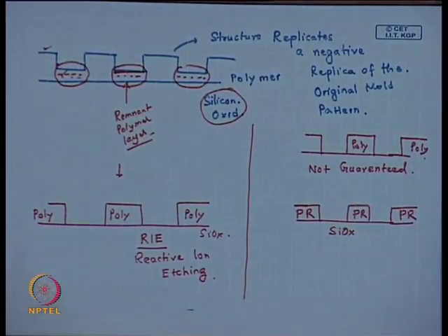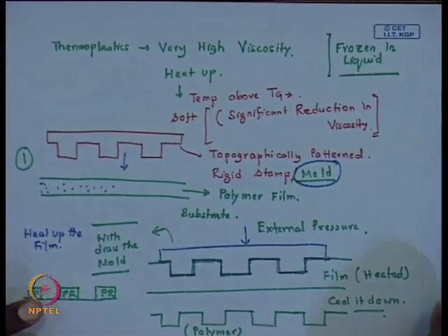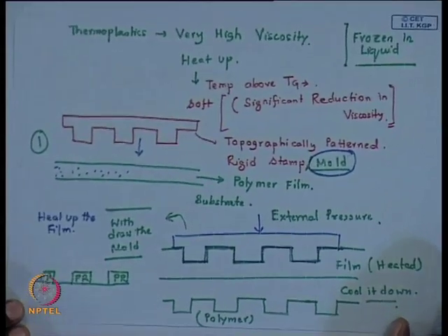So, in principle, a nano imprint lithography group of techniques also has the potential to be used in the fabrication of microelectronic components, but its scope extends much beyond that, and for bulk nano application as well as rapid prototyping, nano imprint lithography is one of the easiest methods to implement. I am sure we have already discussed the basic principle of nano imprint lithography. You can imagine that understanding the different stages of photolithography took us some 4 lectures, but here it takes roughly 10 minutes to understand. It is so simple.